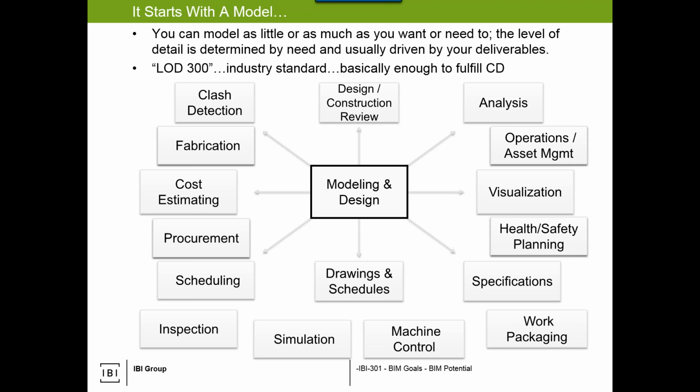The term LOD, and I have a slide about it later, is level of detail. And again, it's a North American term, so for those calling in from other parts of the world, it's really attempted to delineate how much detail. I rationalize it as LOD 100 being schematic, 200 about 60% design development, 300 construction documents, and then anything above is beyond design, so either fit for installation, construction, or operation.